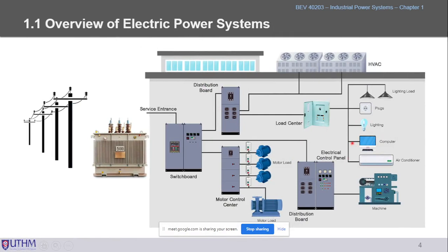Okay, so this is the overall. When we enter the factory, of course this is something like the TNB. So we have the transmission system, and then the first thing you need to design is the distribution transformer. This one, right? The distribution transformer. It is very important, and very costly. A small IPS normally has maybe a few hundred kVA. For a huge industrial consumer, they will have up to several MVA. So they have 10 MVA, 20 MVA, or 30 MVA, and so on.